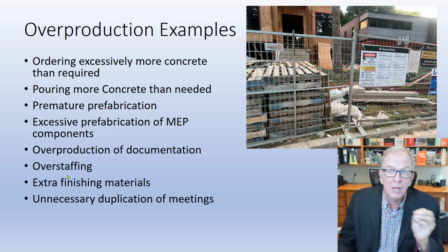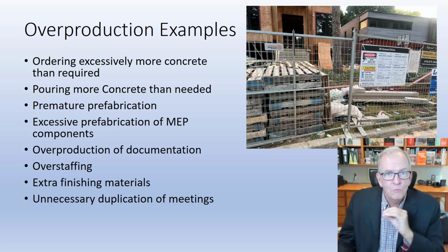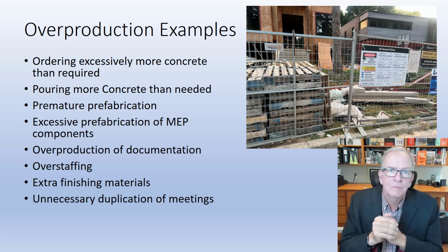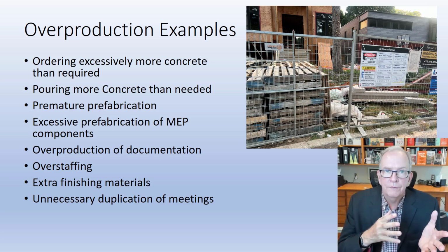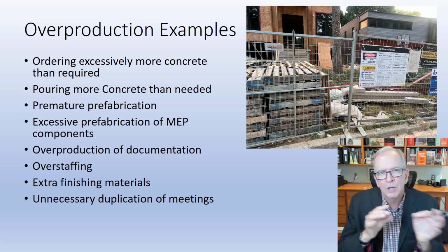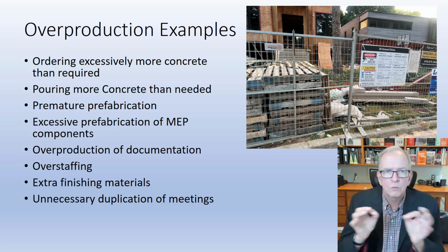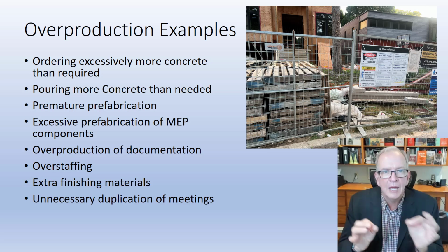Now, again, there's got to be some tension. I would probably prefer to have a little bit of overstaffing if I'm doing a big concrete pour, because the concrete goes off at its own rate, given humidity levels and a number of factors with finishing the concrete. I would rather have more people there to finish it, and if there's a little bit of waste there, that's fine, because of the consequence. Yeah, that's the tension I'm talking about in construction. You've got to look at what it is. But then I would really work on, okay, what is the appropriate amount? And I'd be looking at that, and I'd be testing it.